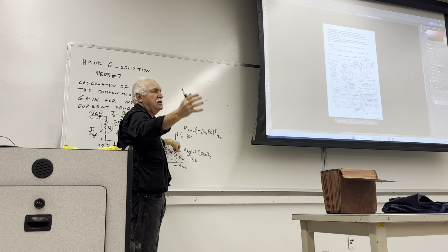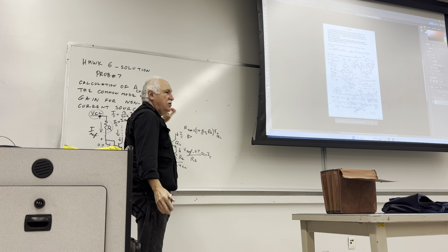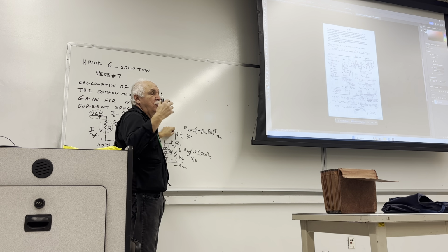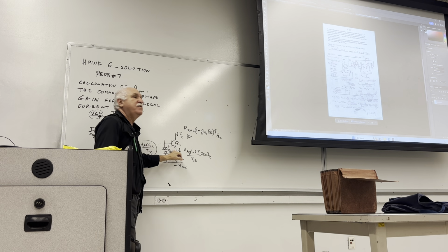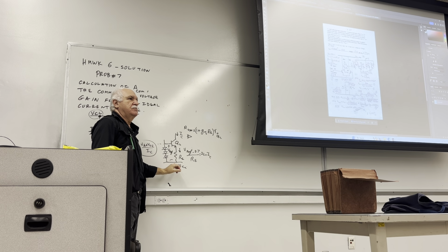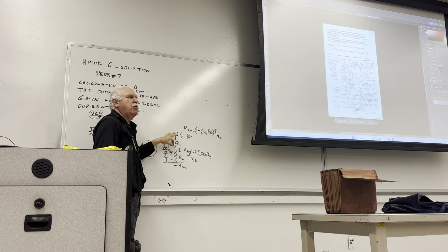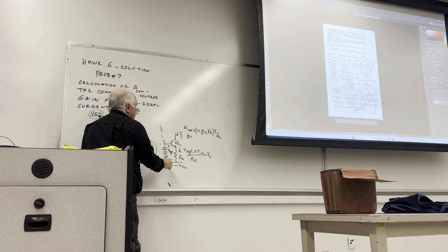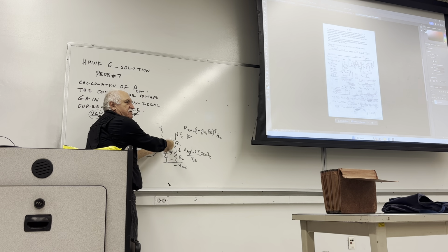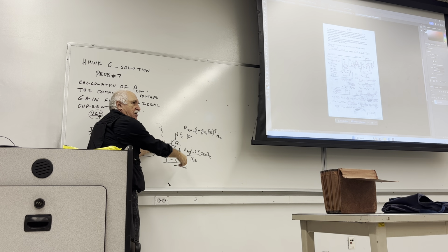That's the bottom line with current sources. Improved or increased dynamic resistance with the help of a resistor at the set bias point. How is this thing biased? There are many ways of doing it. One can take a voltage divider, the same good old fashioned way that you calculated the DC current in the common emitter amplifier, R1, R2, set it up.